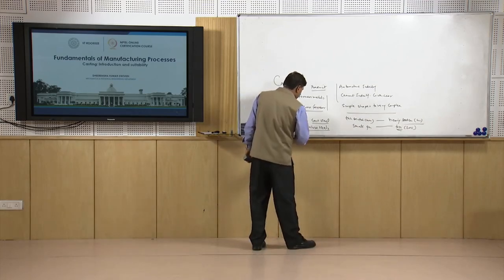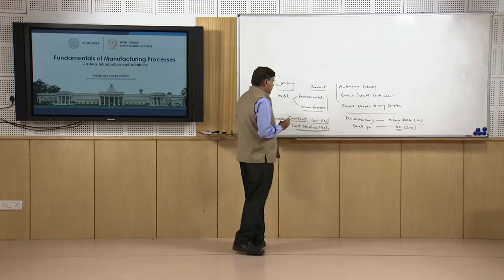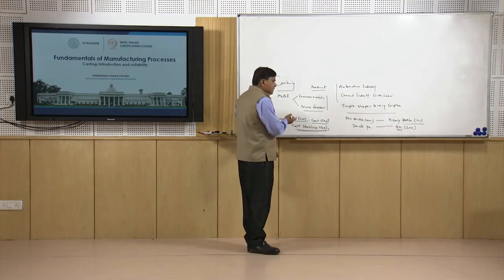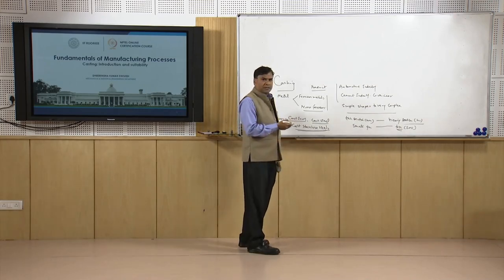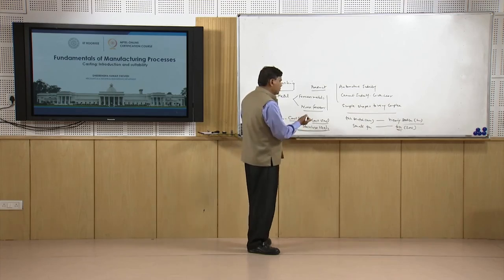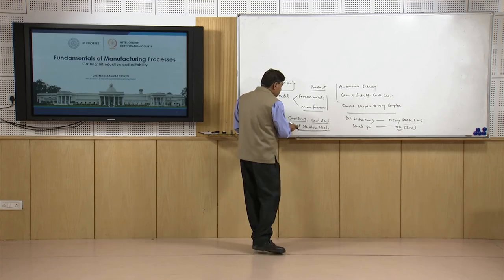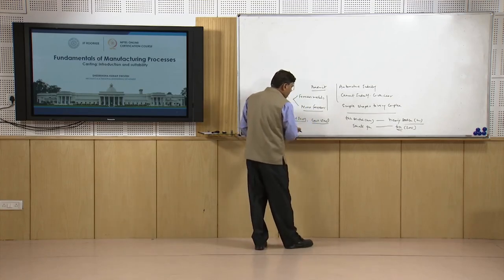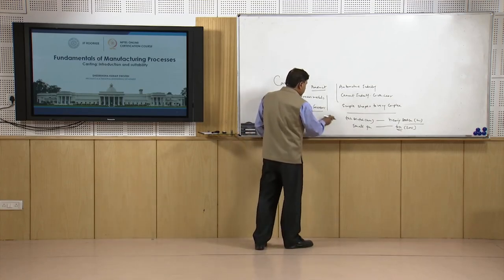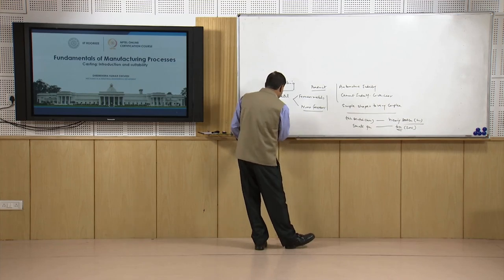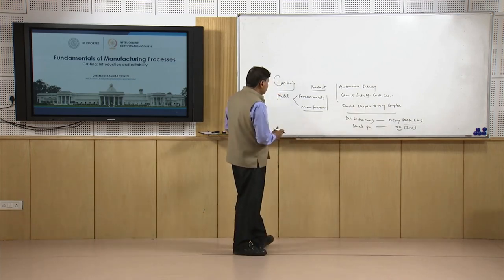where good hardness is required for erosion and cavitation resistance. Cast irons are extensively used because they are cheaper, as well as very easy to cast. So, most of the components used by the municipalities, like manhole covers or benches, and machine beds, are made of cast iron.